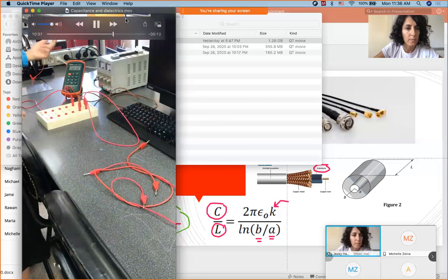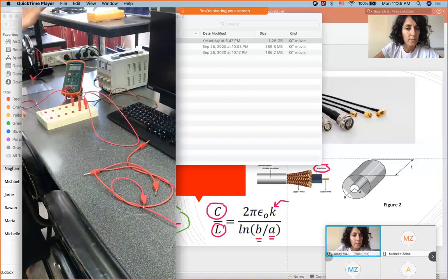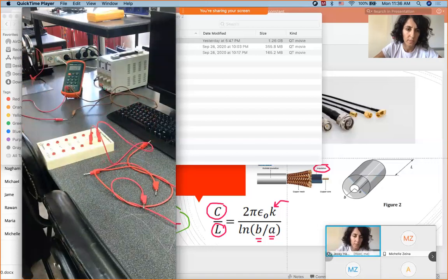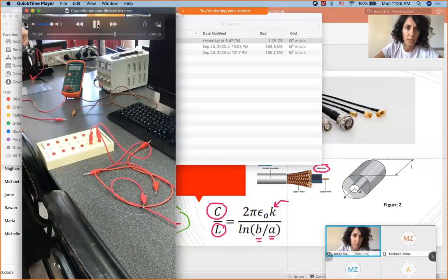So the measurement I will have here is the equivalent capacitance of both capacitors C1 and C2 in series, along with the capacitance of the wire, which I suppose is negligible in this case, so you can just ignore it. For part B, there's no need to subtract this from your measurements, because this capacitance is in picofarads and what you have here is microfarads or nanofarads, which means it would only affect the 5th decimal, so it will not make any change.